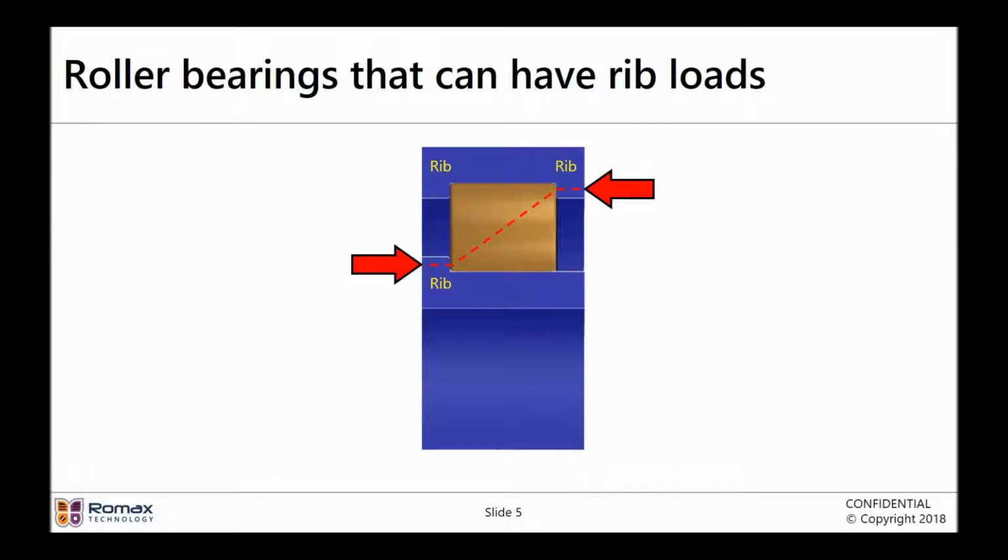Now the intent here is not that it takes a large thrust load. You wouldn't be trying to react the thrust load from a helical parallel gear set. This is really just to keep the shaft from working its way out of the gearbox. For example, if you have a gearbox running north-south in the vehicle or in the machine, and it goes down a hill, there's some gravitational forces that want to move that shaft axially out of the box. This would keep that from occurring.